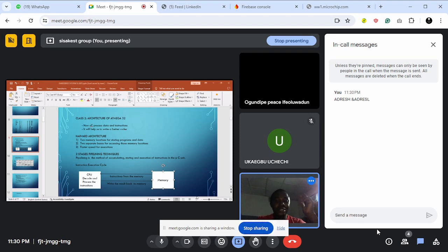The higher one is 8-bit and the lower one is also 8-bit. That's the name of the registers where, the moment you do the ADC conversion, the result of that conversion, whether it is 10, 100, or 150 degrees, is stored in these memory locations.